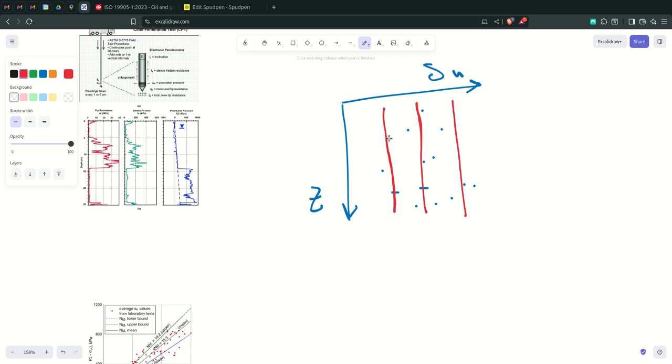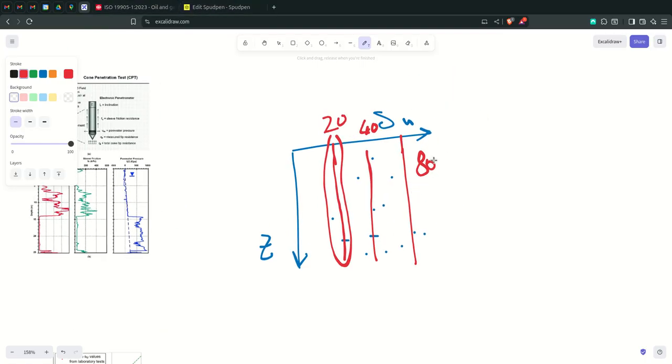So then for each analysis, if you do a lower band analysis, you can select the lower band profile, this line, which for example can be 20. The best estimate, let's say for example, is at 40, and the upper estimate is like 80 kPa, for example. So this is basically the way that you do the analysis for the lower band and best estimate, and basically you have to repeat it.